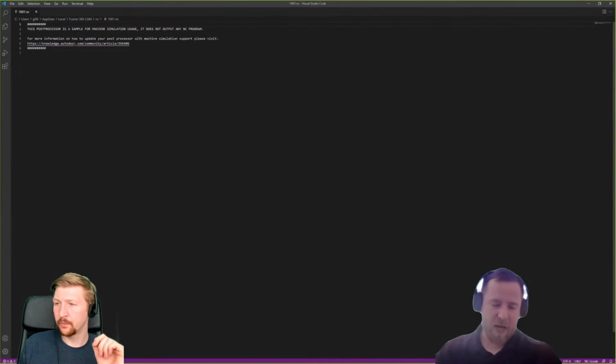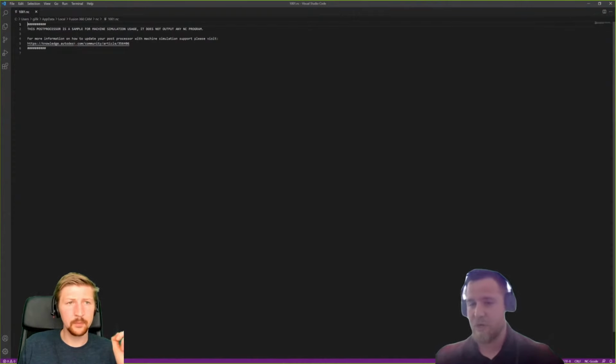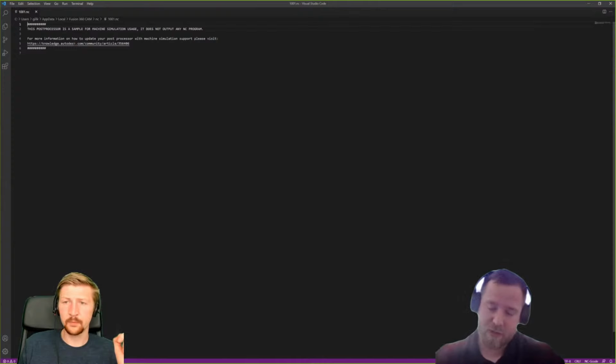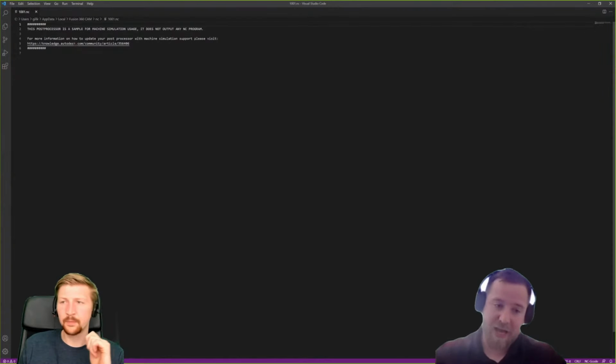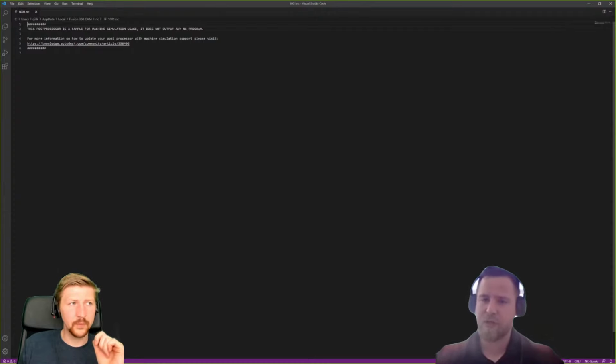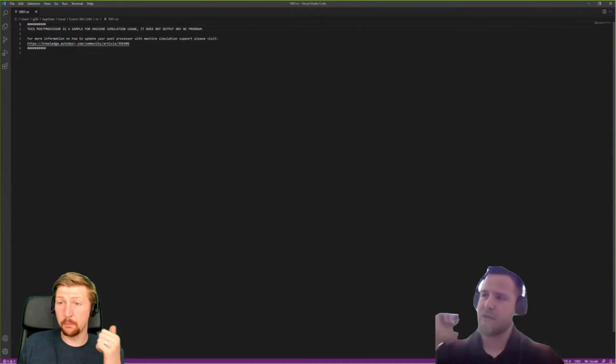Probing is currently not supported in simulation as well, but like with all of these things, when we go to release, we're going to look to support things like collision detection, supporting probing functionalities on the CAN cycles, and supporting the linking moves between different toolpaths, for example G53 Z0s, as I mentioned earlier. So those are all things we're looking to support when it comes out of public preview. Definitely. Okay. Brilliant.